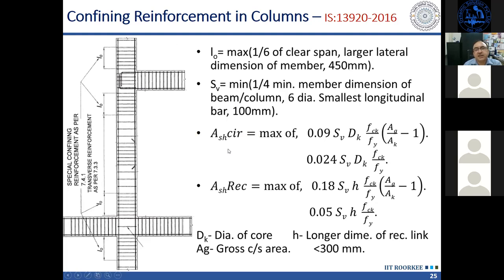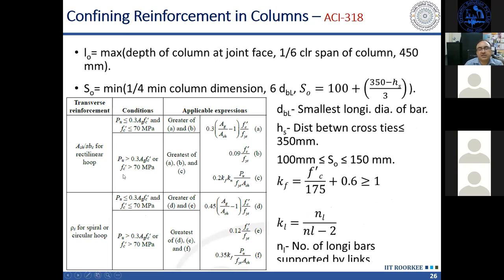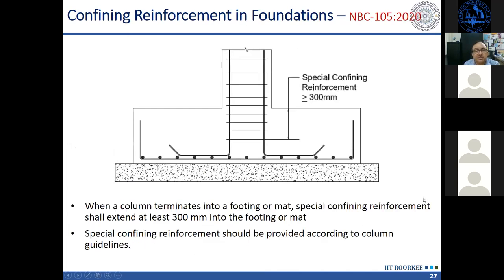Perhaps the understanding is that in our countries, we are still not using concrete greater than 70 MPa. 70 MPa is very high strength concrete. That type of concrete is not used in our countries. So means what expressions are given are okay. But in case in some project, if you are using compressive strength greater than 70 MPa, you have to use these expressions. Those expressions are not valid.